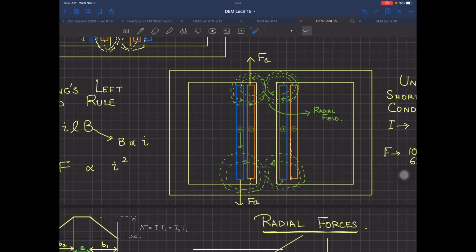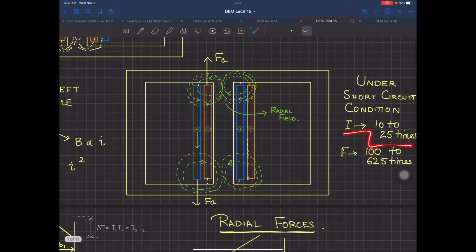आपको याद होगा, in disc winding we did a compression of the whole disc winding because if air is going to be there, force will then go towards that air gap. The winding will be disrupted. And one thing very important, maybe the short circuit does not persist for a very long time. The breaker turns on, it is protected and whatever happens. But in that small millisecond or whatever time it is, the force is exerted.